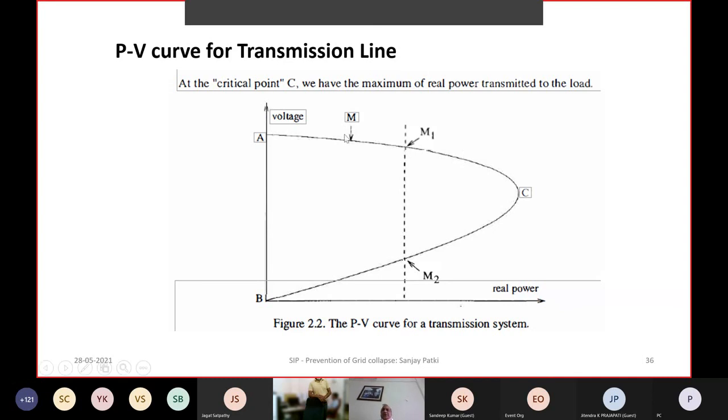Now, when the voltage here is less, what happens to the load which is being fed? When the voltage is low, the motor load on the bus bar, or which is being fed through ICT or any other power transformer, if the voltage is not corrected, will draw more current with a poor power factor.